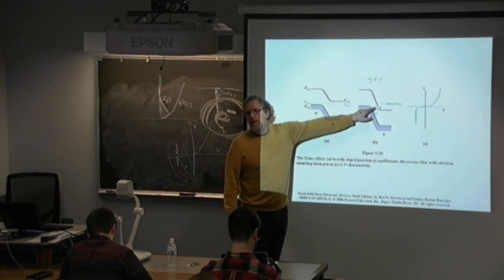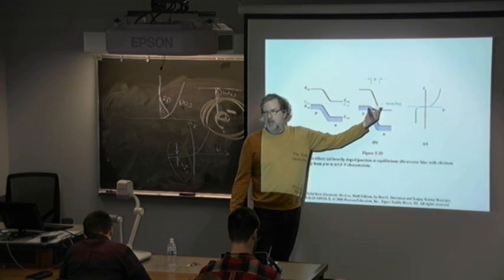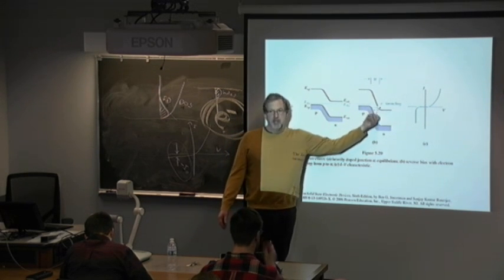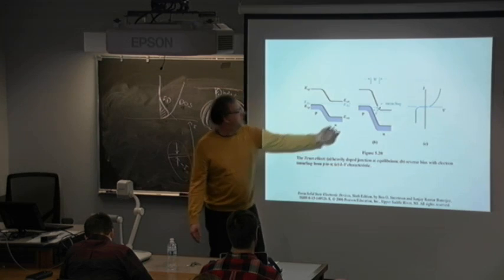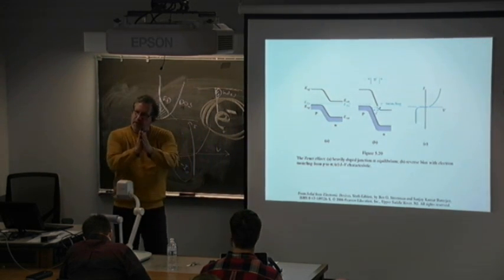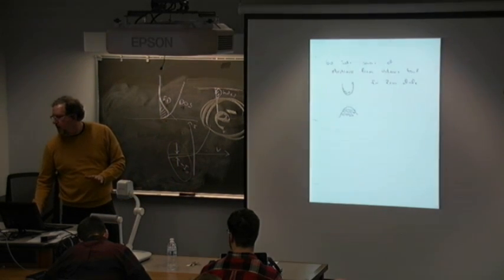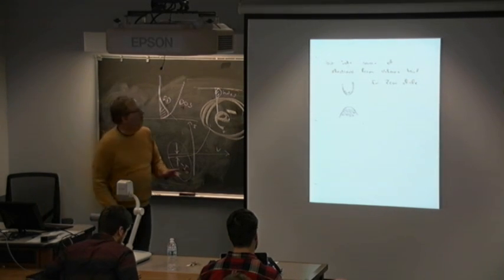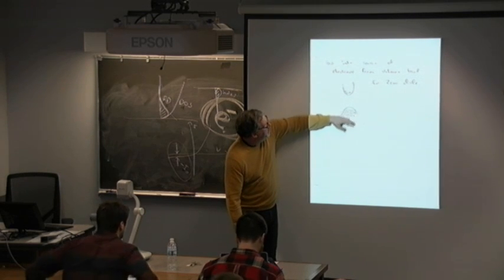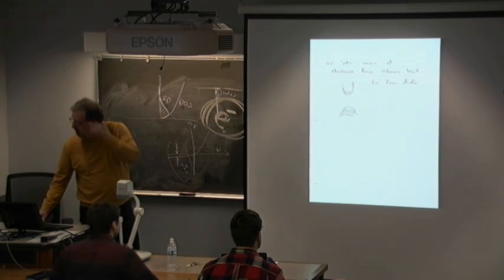In our quantum mechanical devices, usually the preferred quantum mechanical tunneling distance is below 10 nanometers. So if this depletion region is less than 10 nanometers, 100 angstroms, then you might have some tunneling. But if you start to get wider, to a 1 micron depletion region, then probably it's not going to happen. And here I was trying to draw crudely the density of states. Think of it as the electrons, and then you have this little air bubble here. That's why it's kind of a crude cartoon.